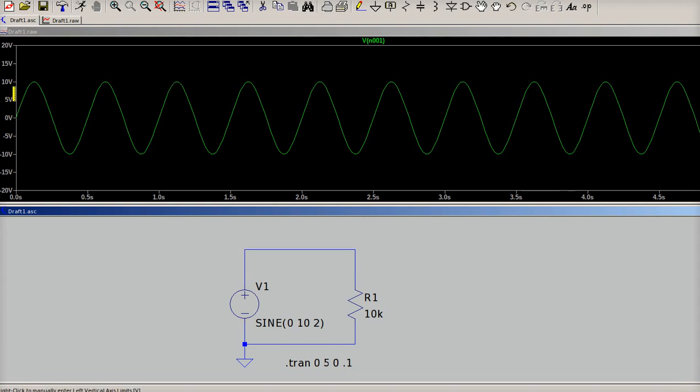From a mathematical standpoint, if I was to make everything positive, and I would do that by squaring, that's part of the root mean squared word, right? RMS, the last word is squared. So if I square all my negative voltages, what do I wind up with? I wind up with positive. And then I'm going to take the square root of it. So basically I would make everything positive.